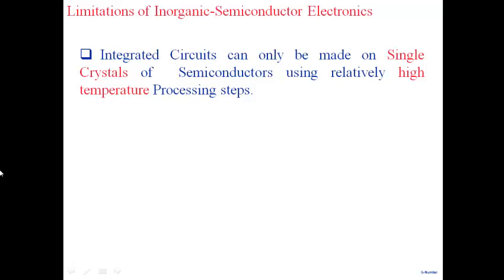Similarly, if I take light emitting diodes, lasers, and solar cells and others, they're also, for example, light emitting diodes may be made on a gallium arsenide substrate. They're also crystalline. If they're not crystalline, none of the light emitting diodes will work. So the point I'm trying to emphasize is that conventional inorganic semiconductors are all made on crystals. If there are a few defects, or if the material becomes non-crystalline, none of those devices will work. Your bipolar transistors, your PN junction diodes, none of them will work properly. So the material has to be crystalline.